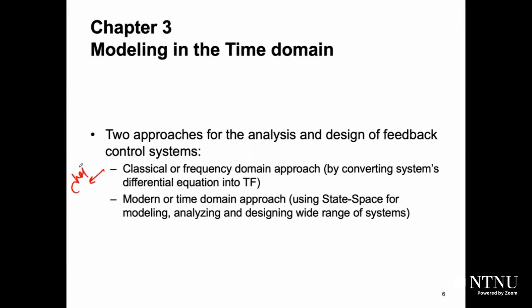So in chapter 2, we can say that this is the classical approach, where we are working with the system in the frequency domain. And to do this, you need to get the transfer function. And to get the transfer function, you need to convert your system's differential equation into a transfer function using the Laplace transform. And therefore, we studied the Laplace transform.